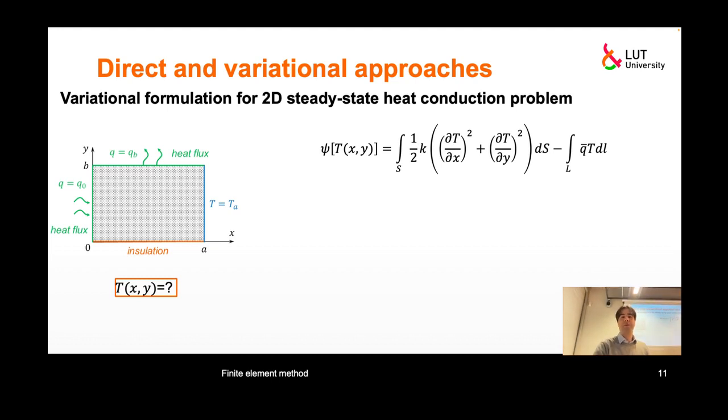Let's say we are looking for a solution of this two-dimensional elasticity problem. Oh, sorry, not elasticity, heat conduction problem. It's a little bit simpler than elasticity because we have one degree of freedom at each point. We have only one unknown quantity, it's scalar quantity temperature. In elasticity, it's usually a two-dimensional or three-dimensional vector, displacement vector. Of course, you can also formulate a one-dimensional elasticity problem, and I will actually ask you to do that in your home assignment.